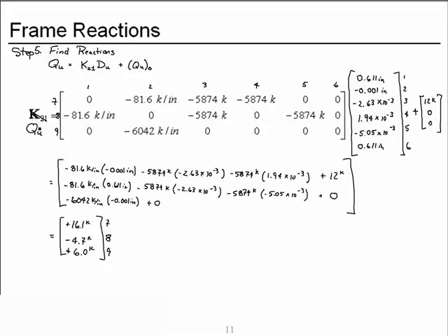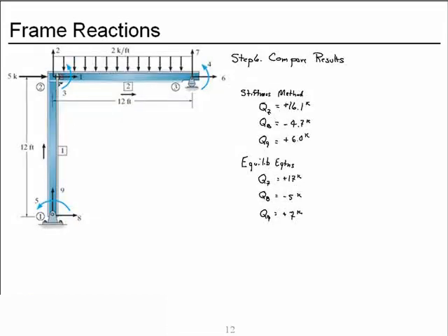And in our calculations for the reactions, we introduced subtractive cancellation again, which is even more round-off error. So I think it's reasonable to conclude we have properly applied the stiffness method, but what we have learned is that we probably need to carry more than 3 or 4 significant figures in these calculations if we want to keep our errors below 1%.